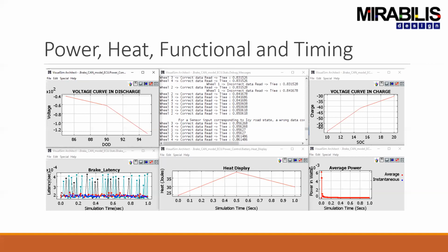So for example, over here, when I look at the brake latency, you can see the rear and front brake, those receive the data in a very, very small band of latency. But when you look at the rear brakes, you can see the range is pretty substantial. Here you can go 300 to about 400 microseconds, almost a 33-34% difference between the best and worst case. So what we're seeing over here is that there is significant blocking or buffering, or maybe something's wrong with the scheduling on the networks connected to the rear brakes. So that's something that needs to be configured.